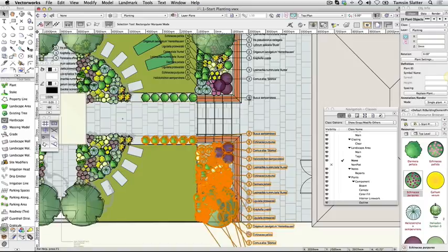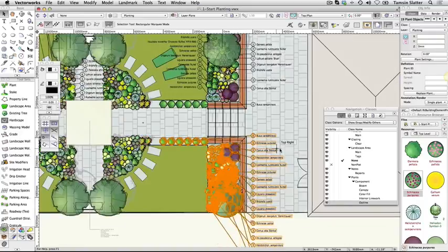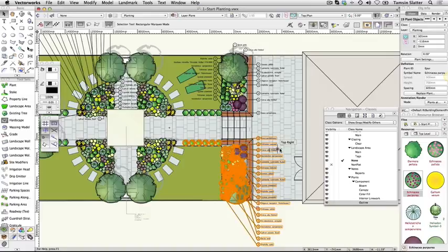To save time, we've moved all the tags to the right. However, you could have selected only the plants on the left of the planting bed and used the Align Distribute Leader Lines command. Then you could have repeated the process for the tags on the left.